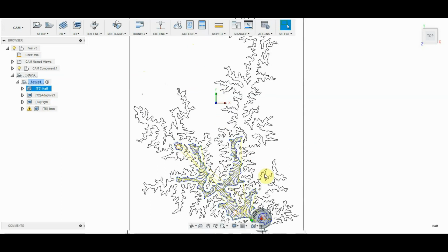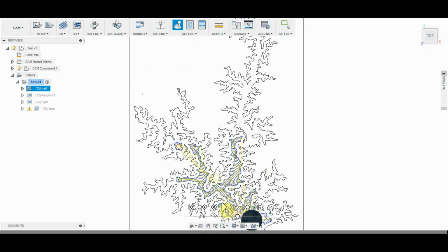The toolpath is what tells the router, the computer-aided router, where to move around and how to cut out what you need. In our case, we chose a 1/2" bit, and what you're seeing is the end result of probably about an hour of computer-aided machining time in order to generate the toolpath. I'm going to simulate it. It's kind of interesting to watch it run. What you're watching is what actually will happen on the CNC machine, although sped up quite a bit.